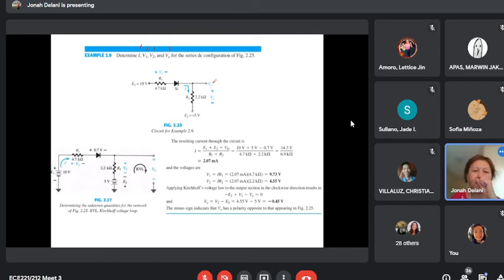If we measure VO with a voltmeter, the positive probe would be at VO, of course, with respect to ground, so the other probe will be connected to ground. The end of the resistor is at negative 5 volts, not ground. So this time, VO is not the voltage across the resistor. I hope that made this very clear.